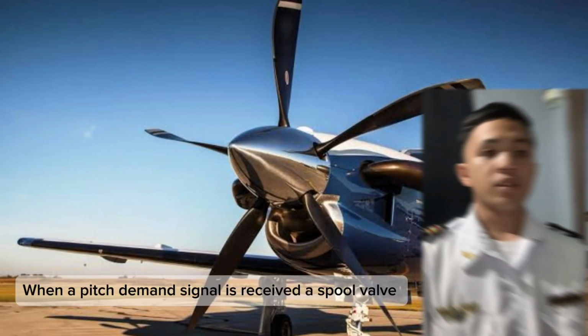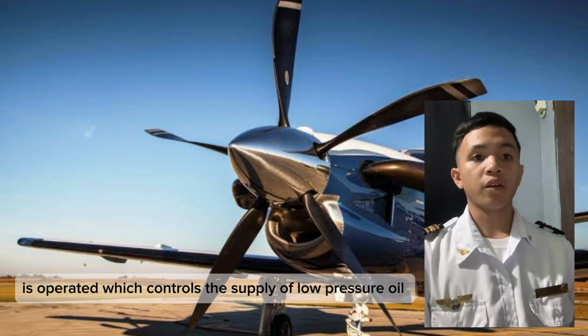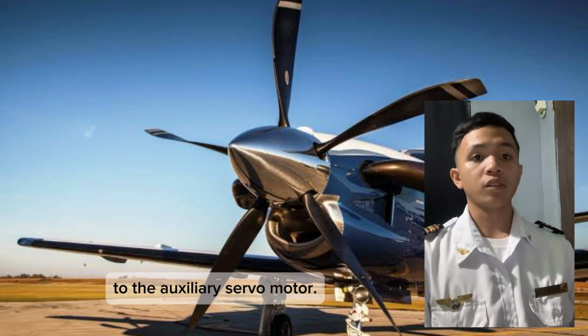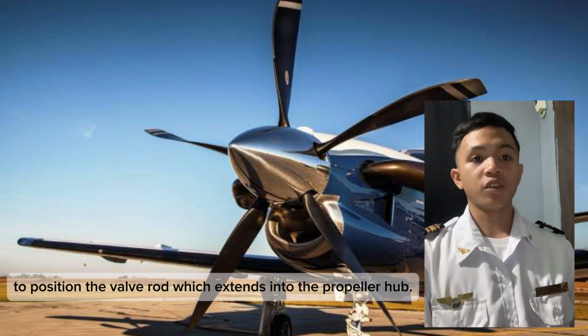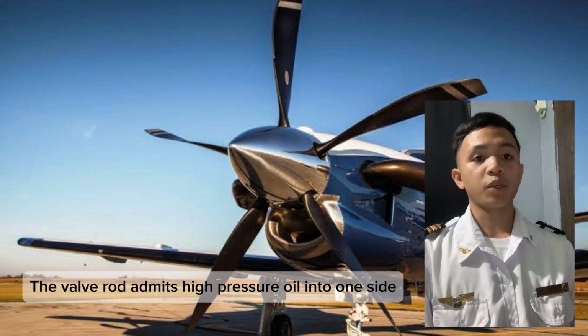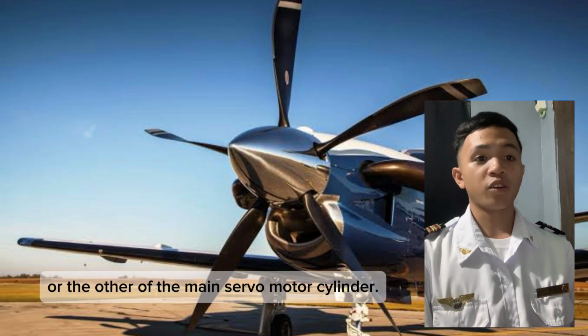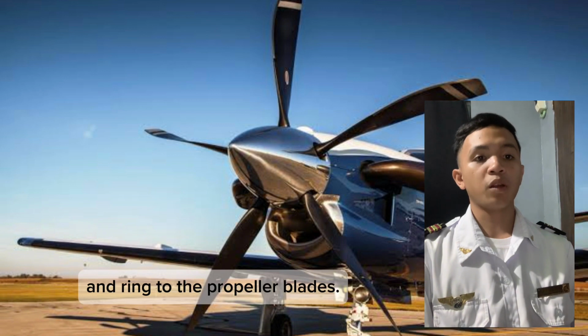When a pitch demand signal is received, a spool valve is operated which controls the supply of low-pressure oil to the auxiliary servo motor. The auxiliary servo motor moves the sliding thrust block assembly to position the valve rod which extends into the propeller hub. The valve rod admits high-pressure oil into one side or the other of the main servo motor cylinder. The cylinder movement is transferred by a crank pin and ring to the propeller blades.